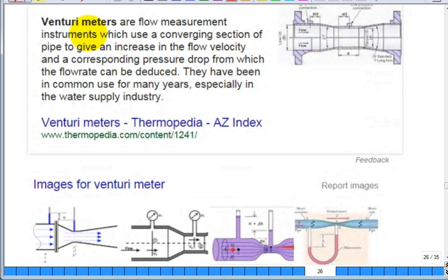So what's a venturi meter? You just reduce the cross-sectional area. What's the flow going to do? From Bernoulli's, what's the pressure going to do? Drop. You have accurate measurements of the cross-sectional shape of your meter. You hook up a tube. Here they're showing you a manometer, pressure. Here's a linked manometer. And so from the pressure difference and the cross-sectional areas, you back out the flow. It's that simple.